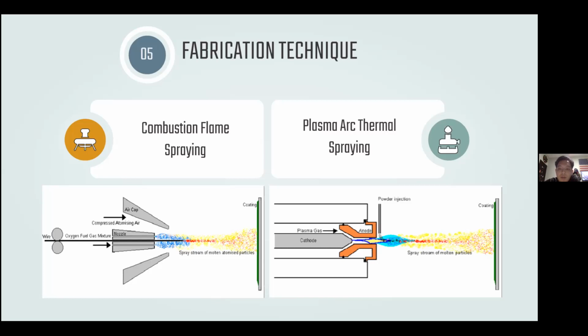The primary principle of this method is to employ oxygen and fuel gas to generate the heat required to melt the wire, which serves as the feedstock material. The wire is usually contained in a spool or coil, which is held on a separate wire holder. It is also fed into a gun by an air-pressurized, electric-powered drive mechanism, where the oxygen and the fuel gas are mixed and ignited to generate a heating zone that is used to melt the wire, and the molten droplets are pushed onto the substrate using a limited stream of compressed air.